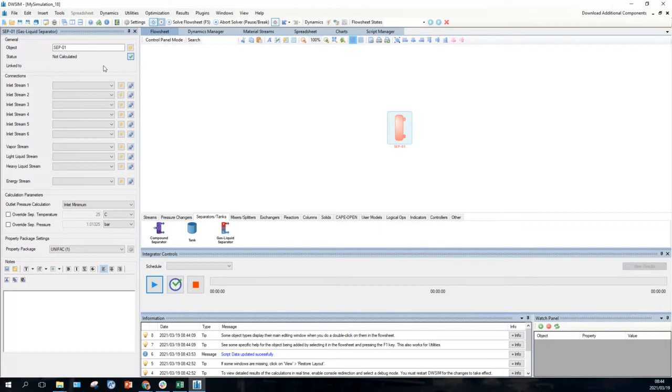So what we need to do is to add in streams. You'll have a single stream coming in and you'll have 2 streams coming out. And for every unit operation, there'll also be an energy stream, because a unit operation typically has a duty, and you need to either add energy or subtract energy or lose energy if it's not properly lagged, insulated.